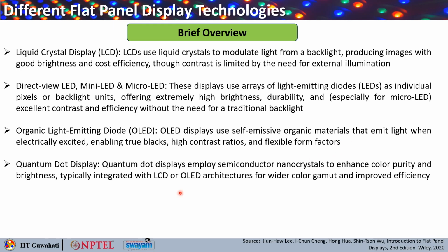Next, these days you may also be hearing about quantum dot displays. Quantum dot displays employ semiconductor nanocrystals, or quantum dots, to enhance color purity and brightness, and they are integrated with LCD or OLED architecture for a wider color gamut, that is the color range they can cater to, and they can also have improved efficiency.